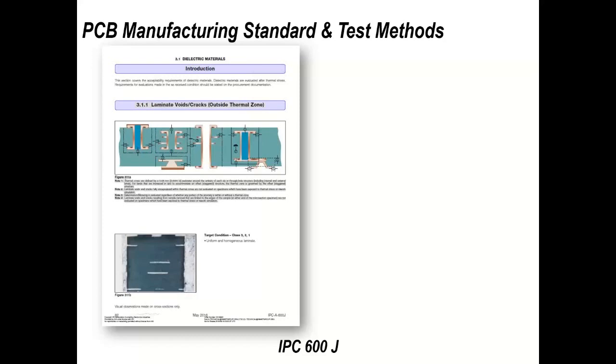Within that you will specify certain things: the size of things, the thickness of things, the plated layers, etc. And all of these things can be examined using a microsectioning technique. The one thing to bear in mind is that with microsection, you're cutting the board up, so it's a destructive technique.